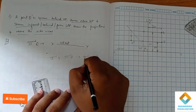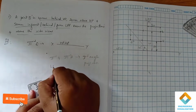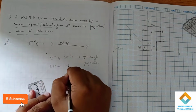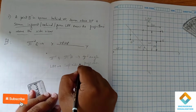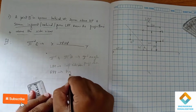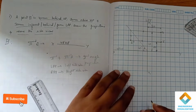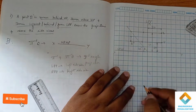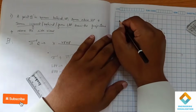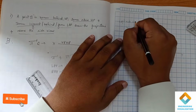In third angle projection, with respect to the LPP we have the left side view, and with respect to the RPP we have the right side view. So this is the left side view, we can write it here: left side view.